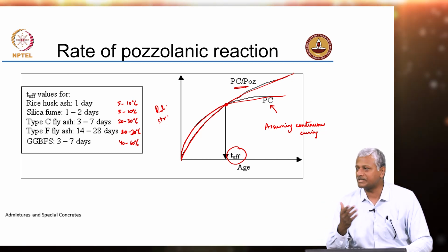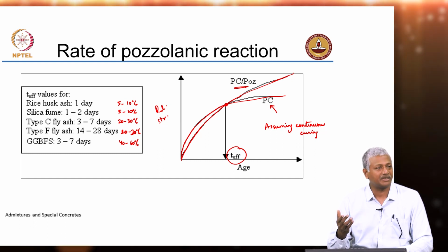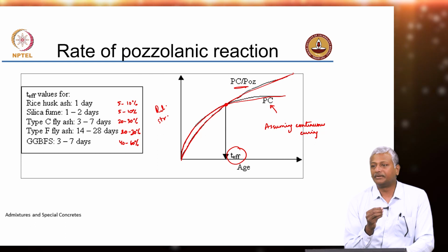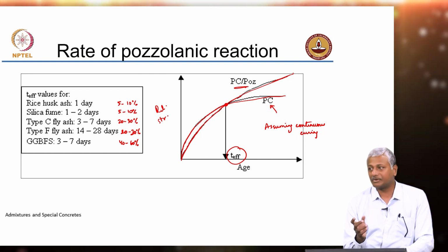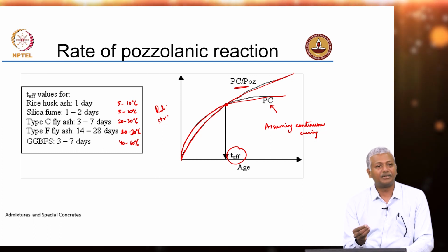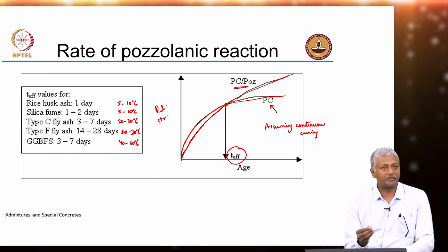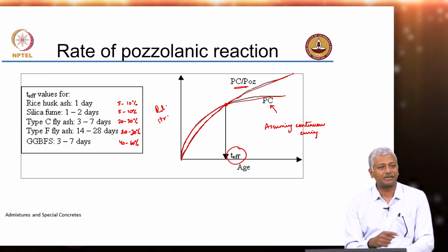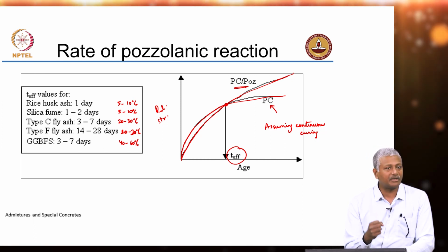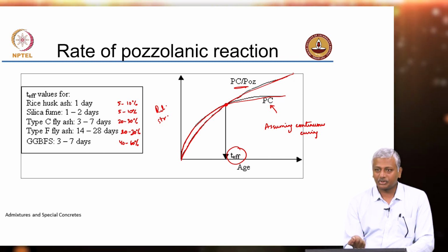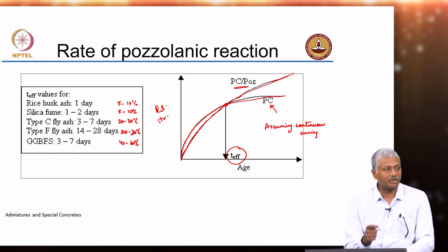You know that OPC 43, 53 are grades of OPC which relates to the strength attained by cement mortar at 28 days. So, PPC 53, actually if you look at the standard for PPC, it has to satisfy only 33 MPa at 28 days, because you want the benefit from its low heat of hydration. But here they started grinding the cement finer and making it react faster. They totally shot down the major advantage of low heat of hydration.